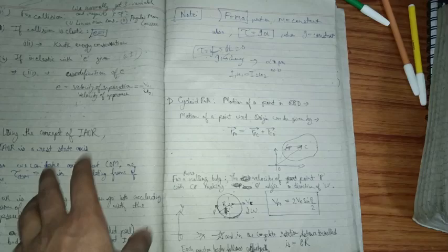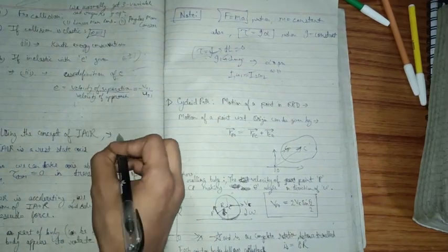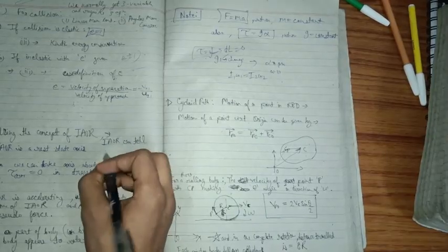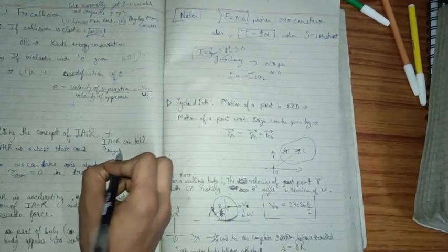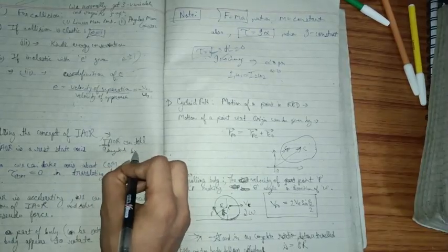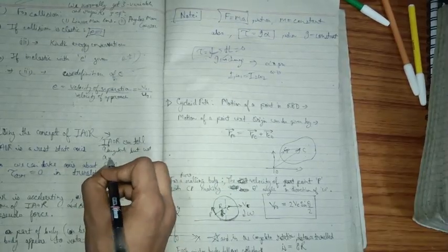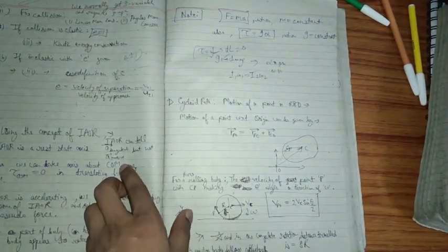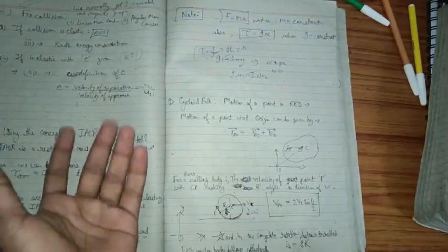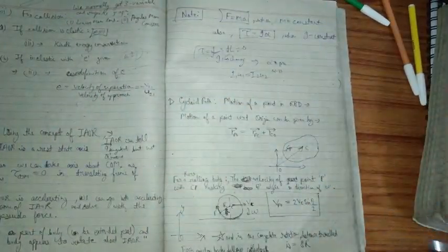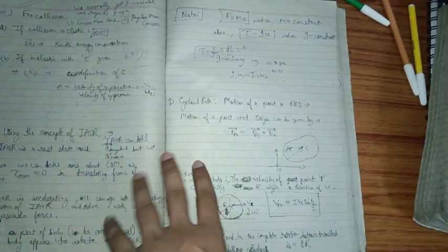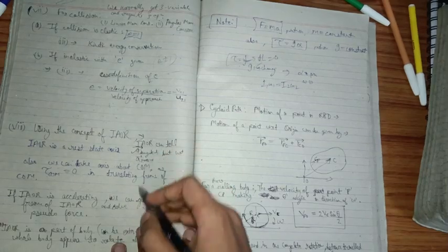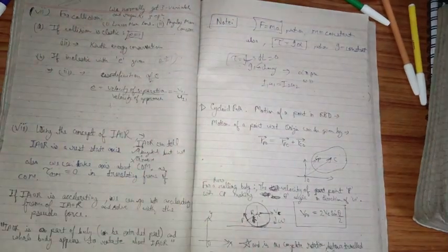IOR concept. In the IOR concept, one more thing: IOR can tell the tangential acceleration but not the radial. The IOR axis cannot tell the radial acceleration, because the IOR is not related to the actual path of the object. It is only dependent on the instantaneous path of the object. So in this case, that is only useful for telling a tangential, but it cannot tell a radial, which depends on the path or the radius of curvature.